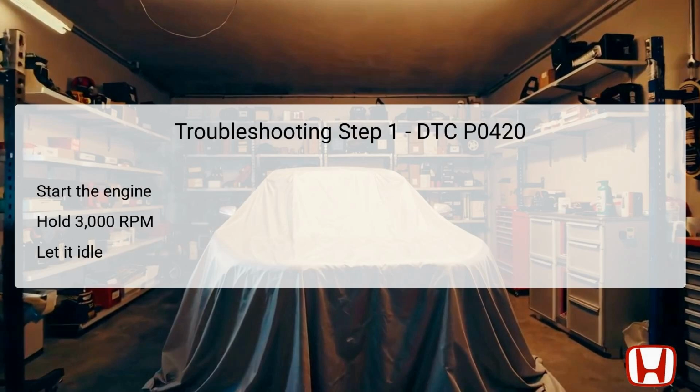The first troubleshooting step involves starting the engine and holding the engine speed at 3,000 RPM without load until the radiator fan activates. This process allows the engine to reach optimal operating conditions, which is crucial for accurate diagnostic testing. After the radiator fan engages, the engine should be allowed to idle, ensuring that the necessary components reach their operating temperatures. This method is intended to simulate conditions under which the catalyst operates efficiently, thus providing a solid foundation for the diagnostic process.